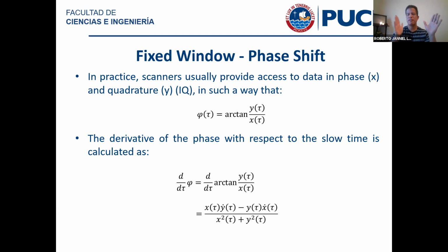When you have a signal that's modulated at a carrier frequency, it will have a certain bandwidth, but just because it's modulated, the maximum frequency within the band is larger than the actual width of the region in frequency domain where your signal is different than 0. So you're wasting bandwidth, let's say it that way, because all the information is contained within the bandwidth of the signal.